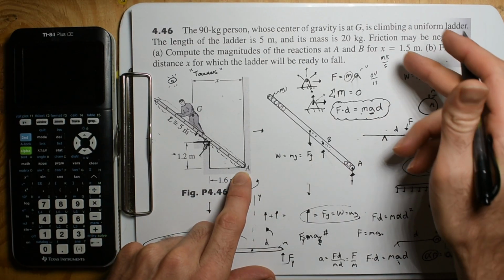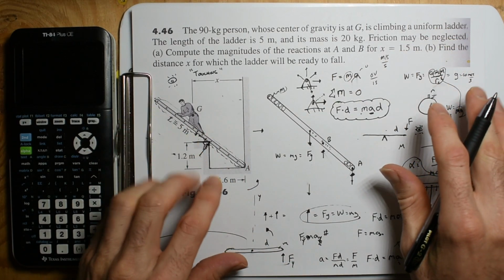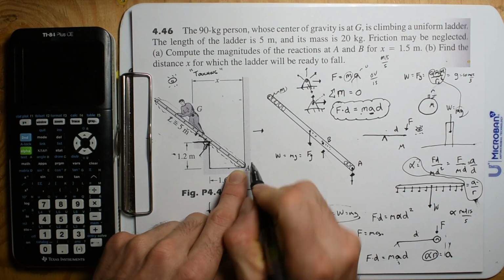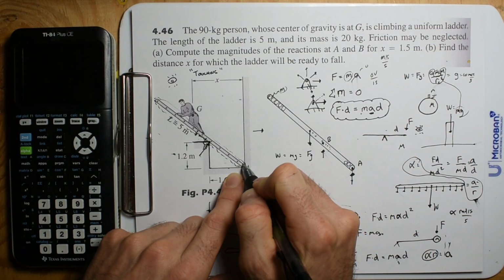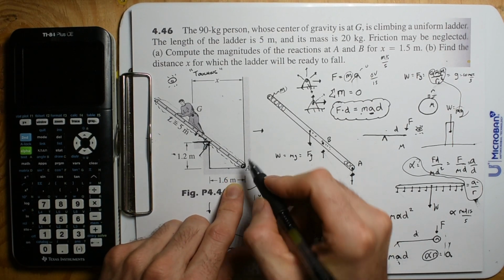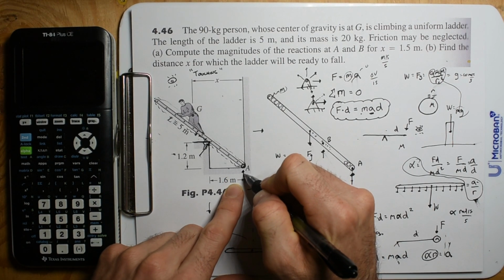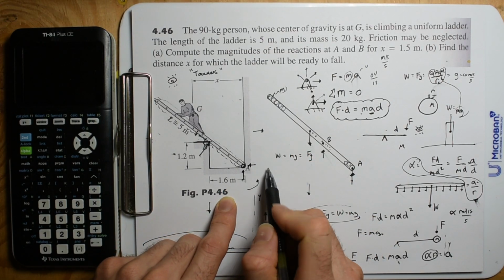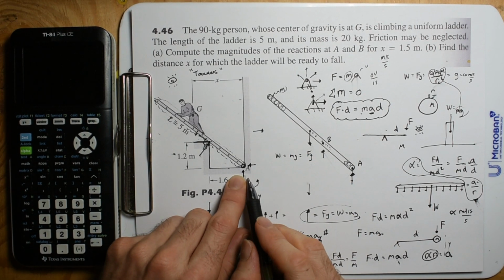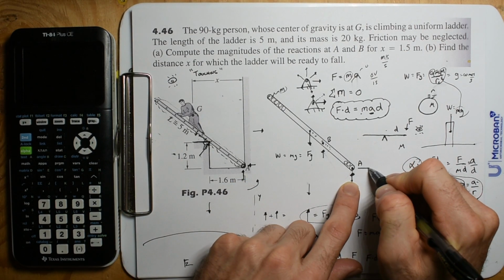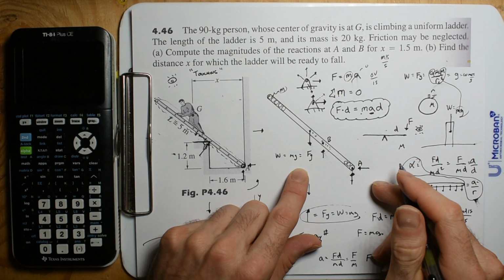And if it's frictionless, so friction may be neglected, what I would do is turn any of your contact points into just a little wheel. So draw a little wheel, and then when you do that, you see, hey, I have a contact point there, upward, and then I have a contact point over to the side. So here are my 2 contact points at A. So now let's kind of draw these in. We can at least draw that we have a force at A.